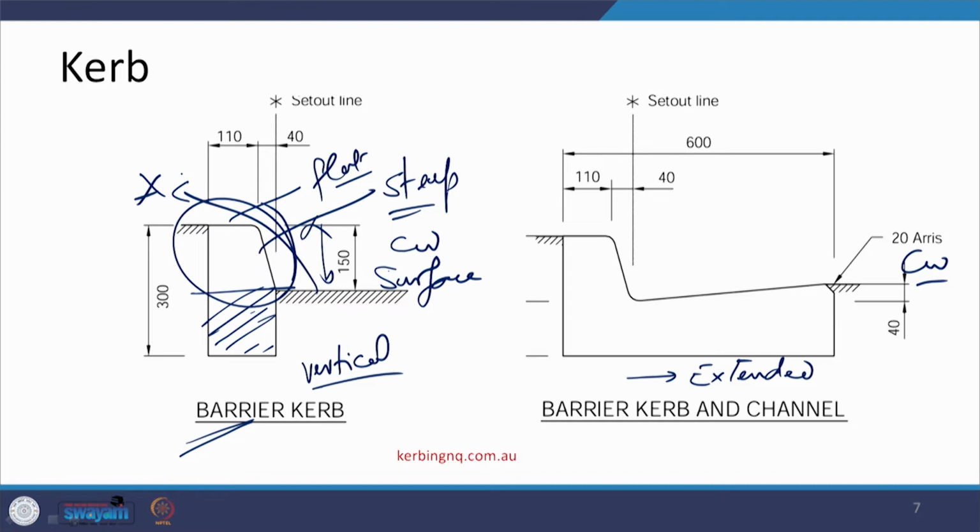design. The extension of this design is being shown here, where the only extension is that we are providing this channel here, and when we are providing this channel, whatever water comes from this side gets here, or whatever water comes from that side gets here. So, you will find that that is a level in which the water is going to be there, and at a certain location this water will be taken out of this particular channel by way of the subsurface drainage system or the internal drains which are being created connected with the sumps.